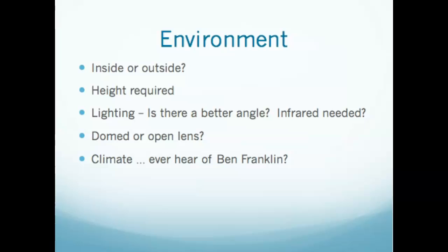The box-shaped ones, those Pelco cameras I showed you, and some of you took some pictures of those up high on the sheets in Slippery Rock or other places maybe, but they were like the boxy ones, right? They sit outside and they kind of look like a little cannon. If you ask me, they're kind of squarish though. I'll consider that an open lens. Yes, it has glass over the front, but it's not domed. But they get a lot less condensation on those, and they have the little overhang built on the lens itself that protects it some from the rain. It's got a little awning, if you will, over the top of that glass shield. So you have to consider the environment there.